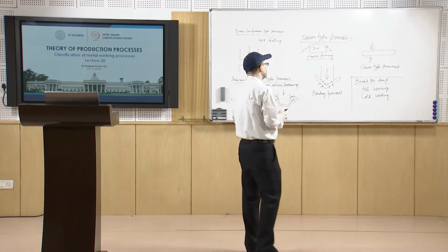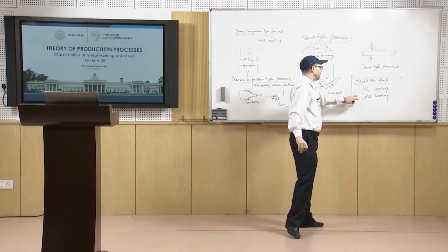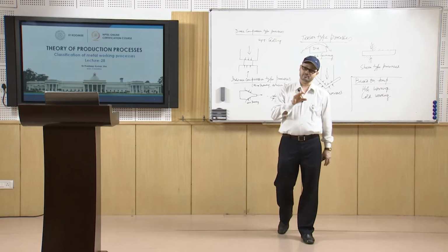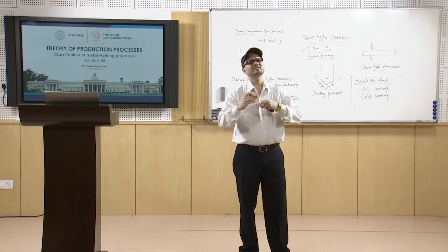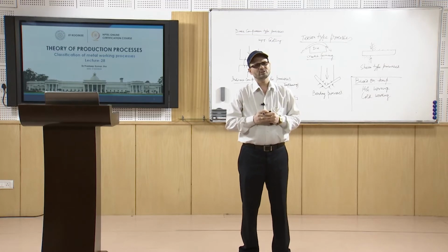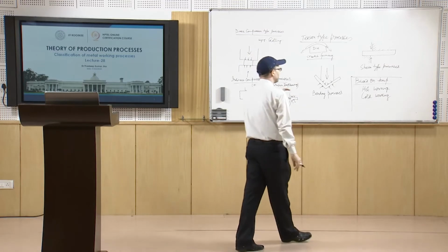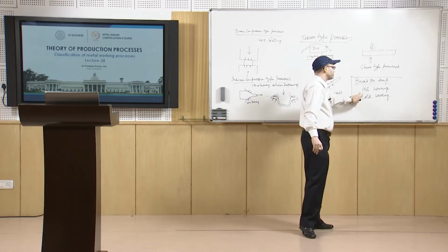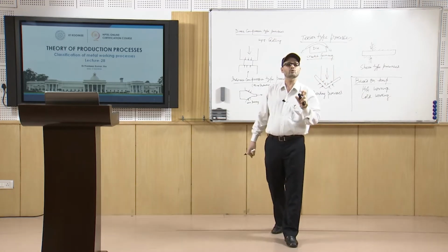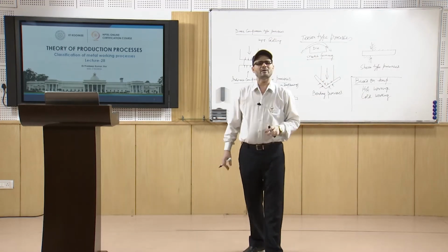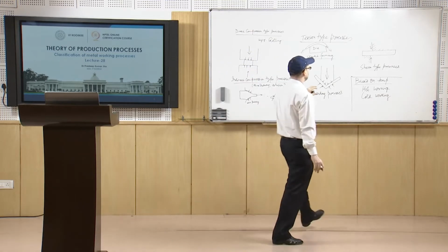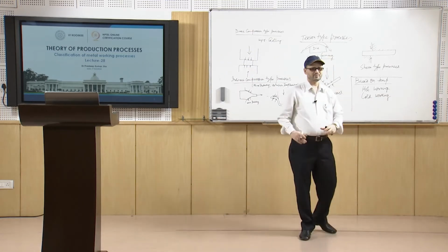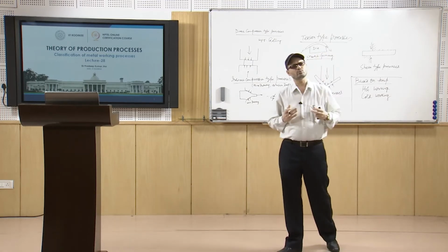As the strain hardening takes place slowly, the flow stress requirement for further reduction in the cross section increases continuously. So, there will be a limit up to which you can cold work the material. After that, when the stress value reaches quite high, the material may fail if you still try to cold work.